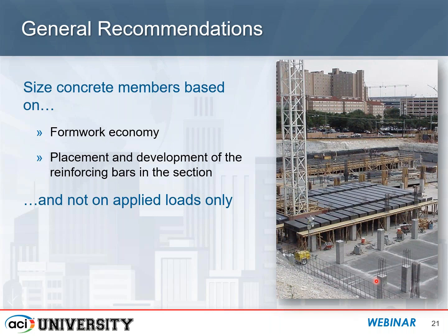Another thing you see, I saw one time there was a beam schedule that had over 100 beam sizes on that schedule. And I'm sure that could have been consolidated, developing typical beams that you can use in many different places and keeping the same width and the depth over the entire span and just varying the amount of reinforcement. That's what we're talking about here.